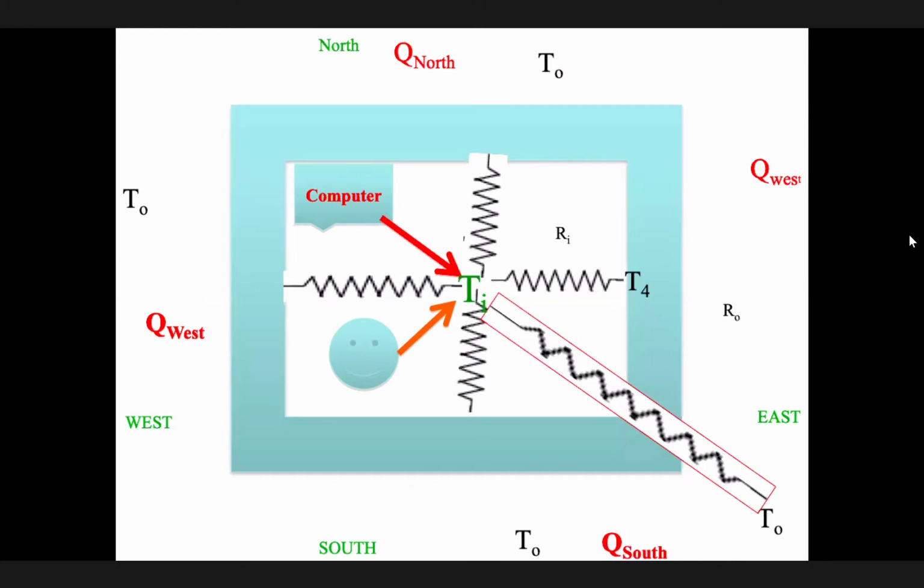How many nodes do you have? I have 18. Okay, 18. You have 18 equations and 18 unknowns. And make sure those variables that you know, you take to the right-hand side. Remember, you have a matrix. A is the coefficients that you have. Yeah, when you have, for example, TO as a known value, you take it to the right-hand side. These are the numbers, positive numbers, you have to take to the right-hand side.